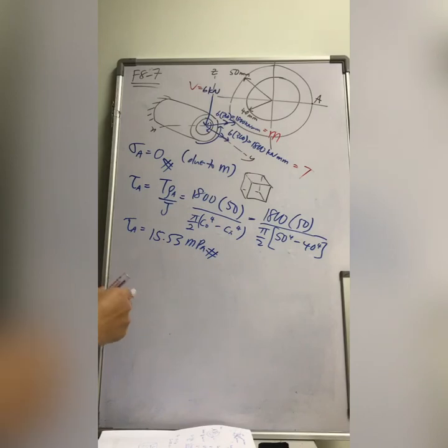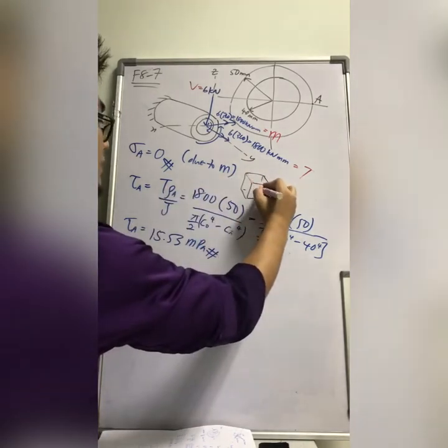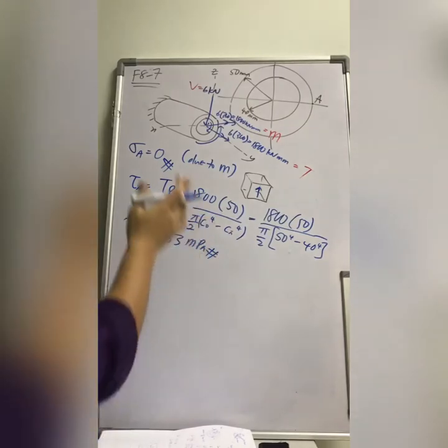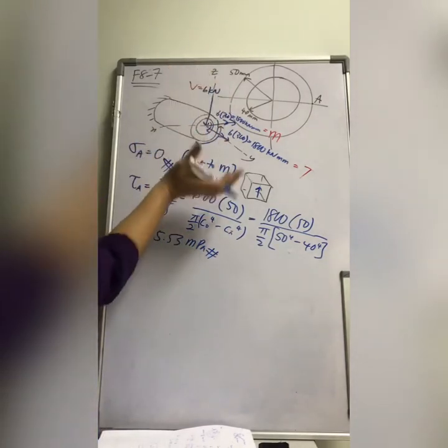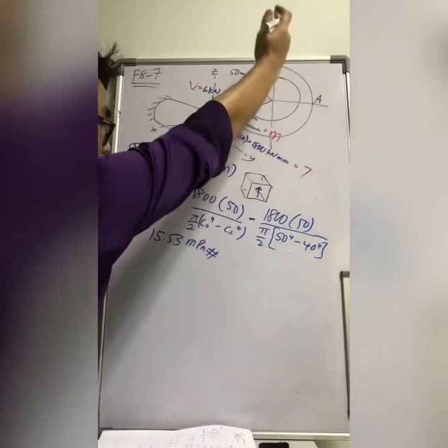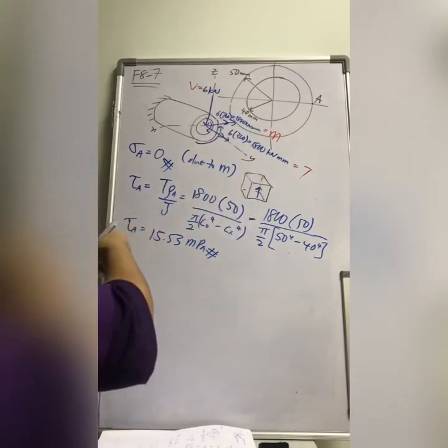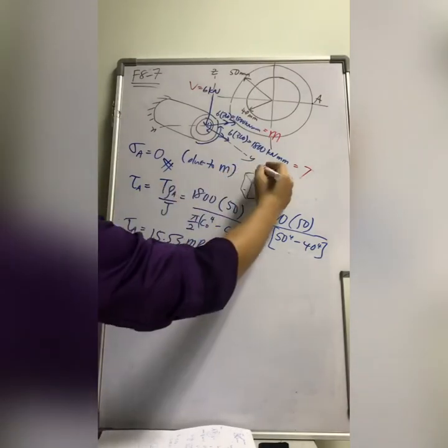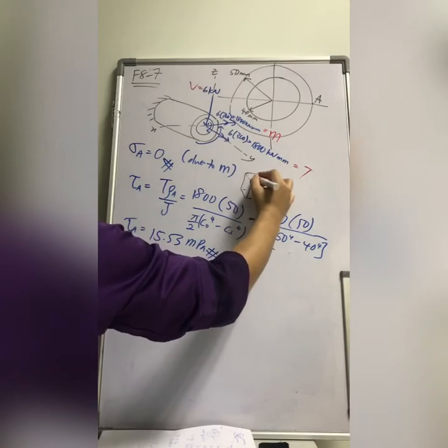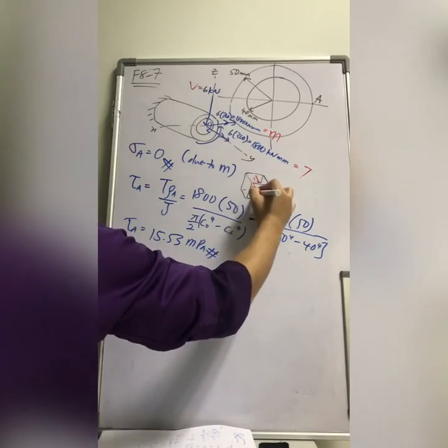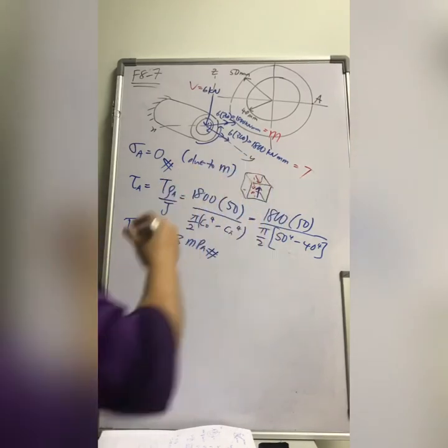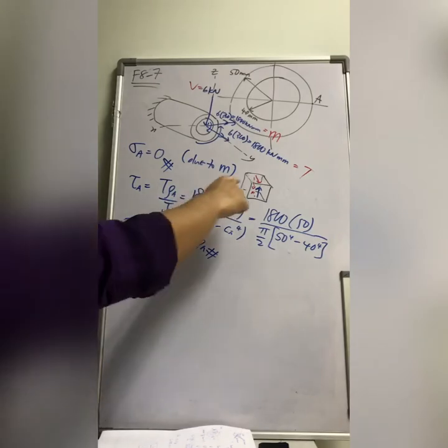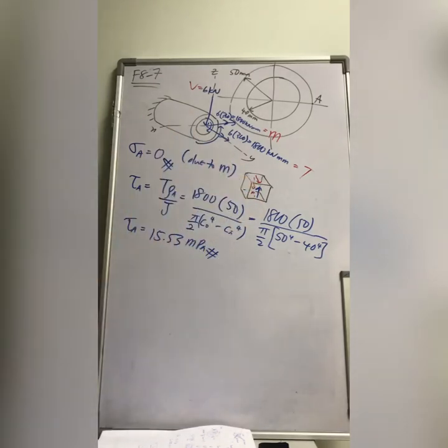You have the shear stress going up, isn't it? Because T goes like this. So A goes up, right? And the rest of the complementary stresses, this, and this. So okay, the main one is the blue one. Of course, the red ones are the complementary. You need to draw those complementary, by the way.